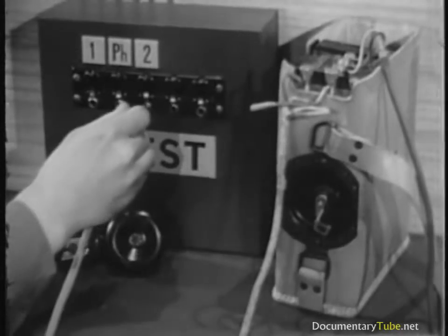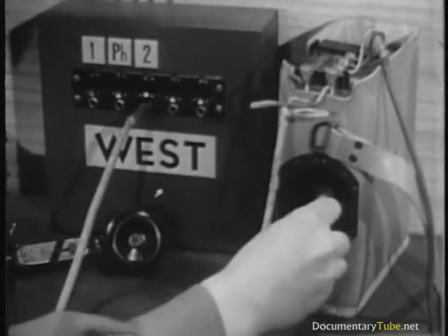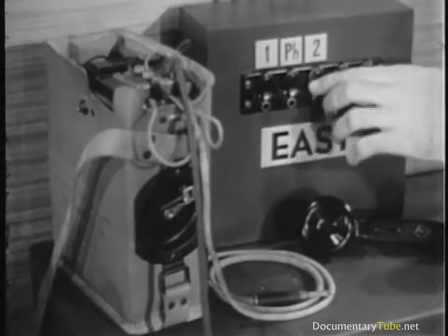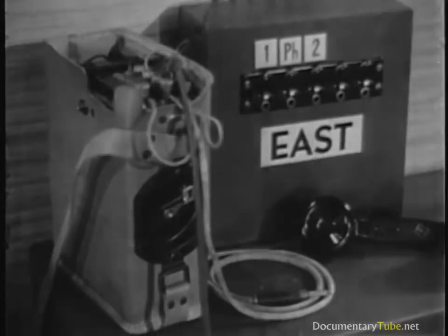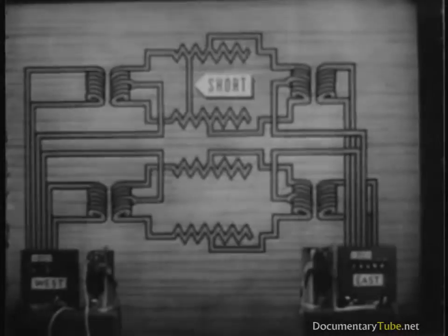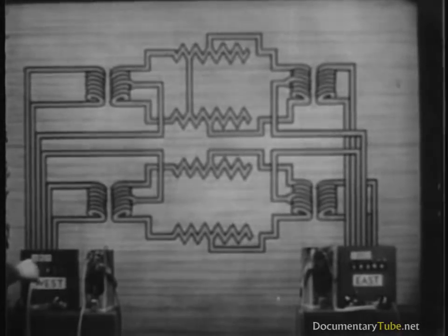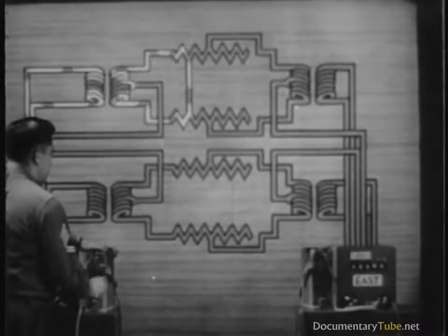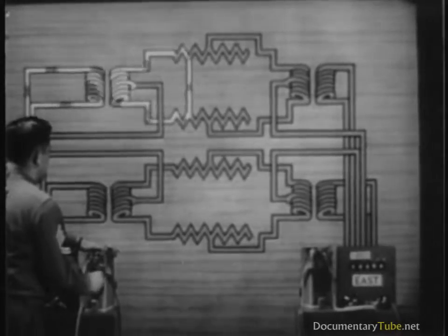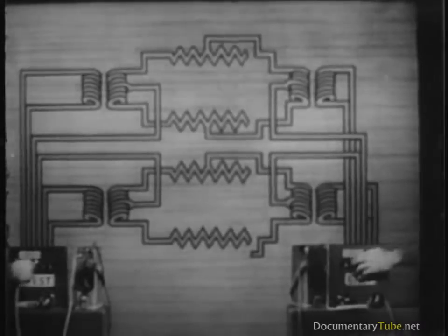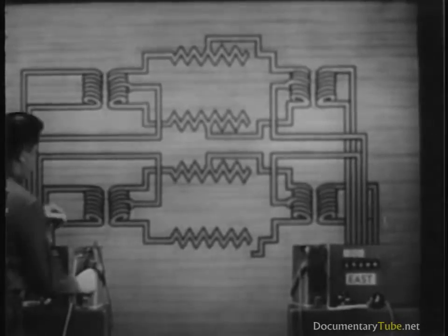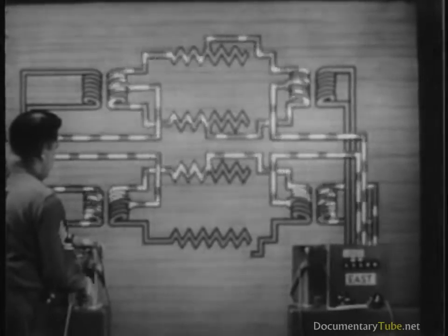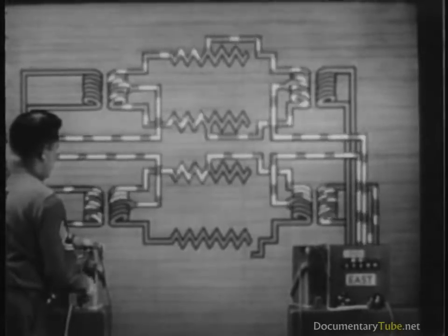What we do have is 2 metallic circuits accidentally crossed, and we won't get any more interference between them than is usually caused by this condition. A short on a side circuit affects only that circuit. An open in one wire of a side circuit causes mutual interference between the side circuit and the phantom.